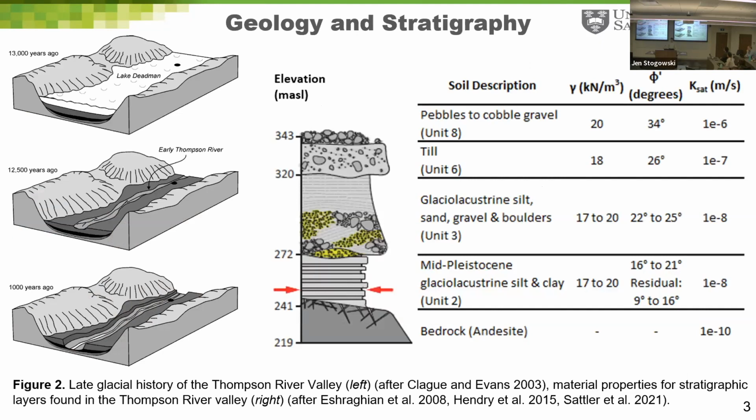The geologic history of the Thompson River Valley consists of sediments from at least 3 separate glaciations from the mid-Pleistocene to the beginning of the Holocene. Successive glaciations eroded the underlying andesite bedrock and previously deposited glacial stratigraphy. Valley glaciers coalesced to form ice sheets and subsequently retreated, creating a series of thin, ribbon-like glacial lakes in the Thompson Basin. As the glaciers stagnated, the ice dam in the Proto-Thompson River Valley was breached and meltwater began to flow westwards towards the Pacific.